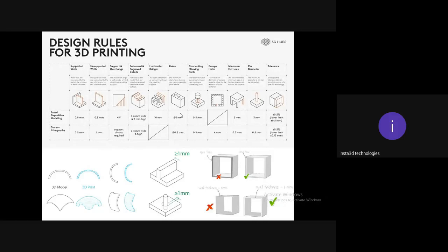So if we keep this orientation, the first orientation, it will form z-axis layer steps, but if we make it vertical, the steps are reduced, but it will sometimes compromise its strength, sometimes compromise its profile, everything. So there are some parameters or constraints for controlling that also.